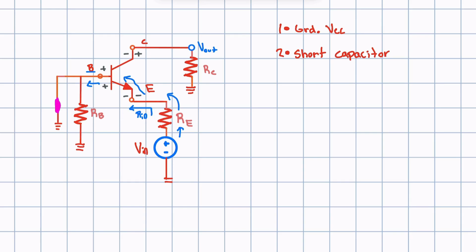Rin is at. Let's make a node right above it, right here. What this means is that as we start going through the circuit in the current direction, direction of Iin, we keep going until we hit that node. And everything before that node is going to be completely ignored in our input impedance formula. So we're going to have Rin, and we're going to ignore everything highlighted in pink.